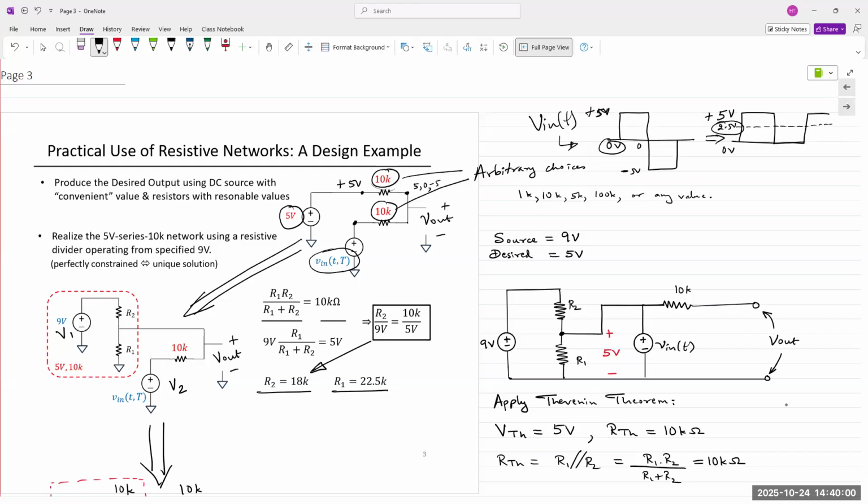So unlike resistors, they will receive the energy, and then they will add it to the energy in the negative half cycle. And so the voltage at the output is a combination of the negative input plus the stored energy in the capacitor. And so there you can get 0 to 10 volts. But that's a discussion for next quarter.